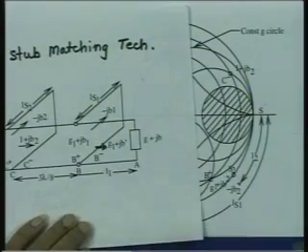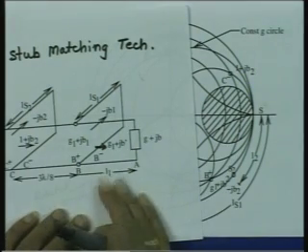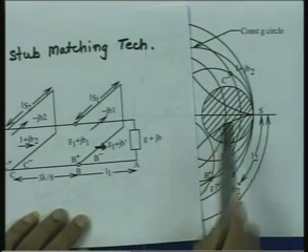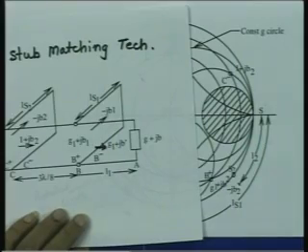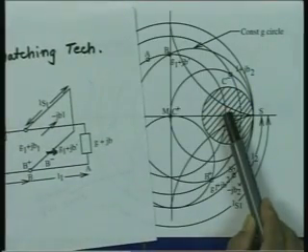So by choosing a proper value of L1, not very precisely, just as a step, there is a possibility that this point can be taken out of the forbidden region. As such, the double stub matching technique has a small limitation: it cannot match those impedances whose transformed value after L1 lies in this forbidden region.